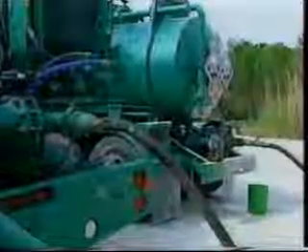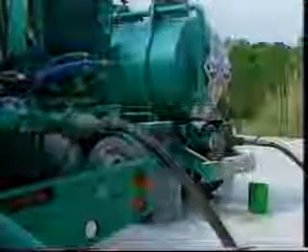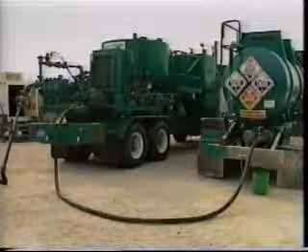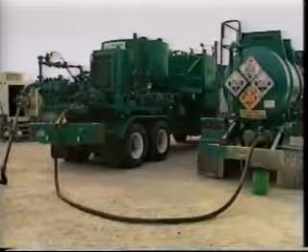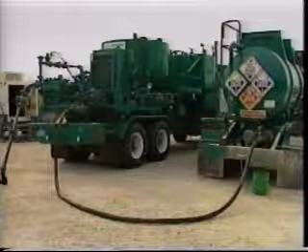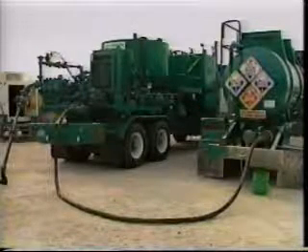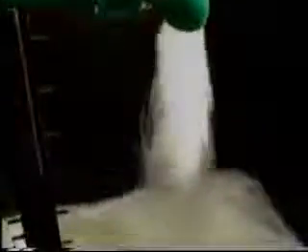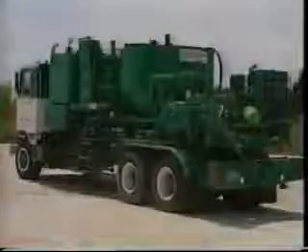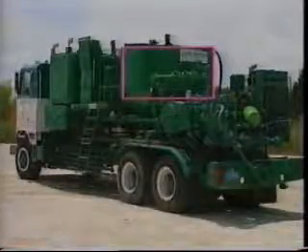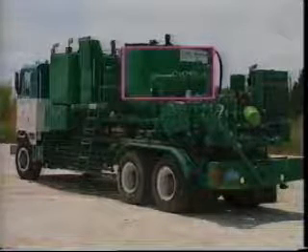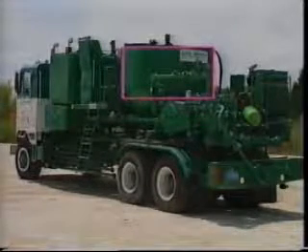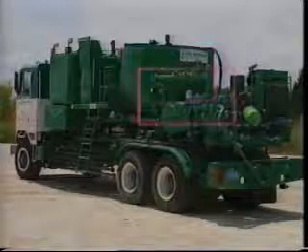Low-pressure lines transfer the treating fluid from the transport to the pump truck. This pump truck is used only for acidizing and gravel packing operations, never for cementing. Such exclusive use eliminates concerns about contamination from other fluids and cement. 2 open 10-barrel tanks located at the front of the pump truck are used to measure the load water. The 25-barrel mixing tank at the rear of the truck is provided for situations where the mixing of gelled fluids is required. It will not be used on this job.